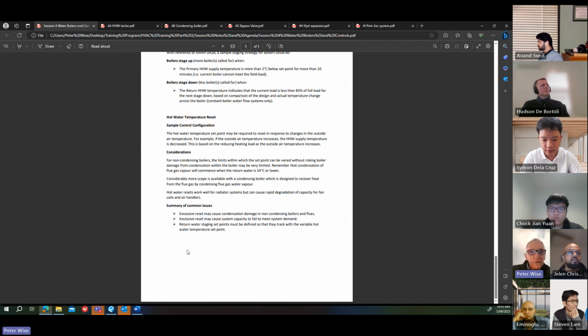So the water can still get out to the field, and the pressure drop through the bypass valve will be very high, but when it gets fully open, the pressure drop should be the same as the field, so that the pump sees the same. The pump doesn't know that there's any difference. It still thinks it's pumping out to the field because it's going through the bypass. So the pressure drop needs to be the same for that reason.